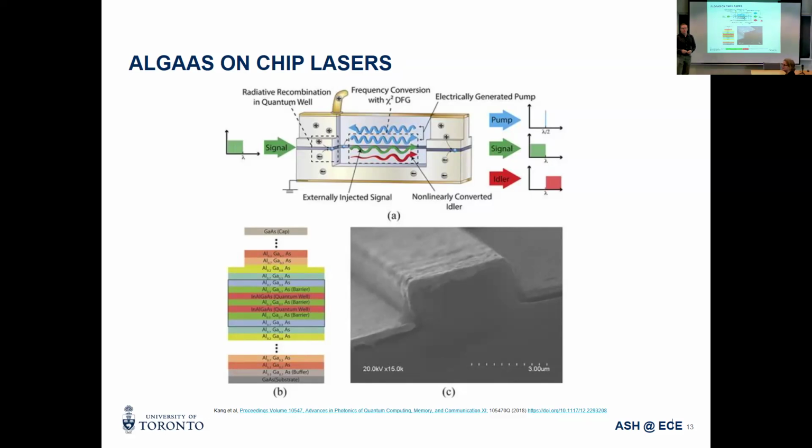For the temperature and these on-chip devices, how important is it to have them in well-maintained conditions? For the LGAS devices, we have them on a temperature stage, so we can tune the temperature. With that tuning we can get redshifting of our signal, of our idler wavelength, sorry, as well. So the temperature is quite critical in controlling the signal and idler, because it's very sensitive to that. Absolutely.